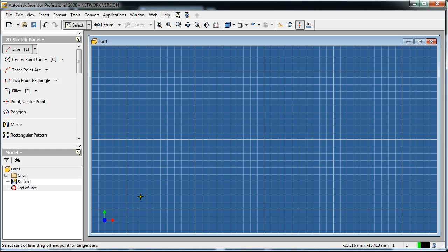So click once on the left mouse button, then you're going to go straight up, click, over, click, down on an angle, doesn't matter, we'll set the angle later, click, come straight down. Now this line needs to be parallel to the other side. You see two parallel signs that appear on the other side and the side that we're currently drawing, and then you trace down until you find an auto snap feature which will connect the dotted line from each of these endpoints, because that is where we will create our next line. So click to anchor that last endpoint, and then one remaining endpoint all the way across, and there's the general shape.